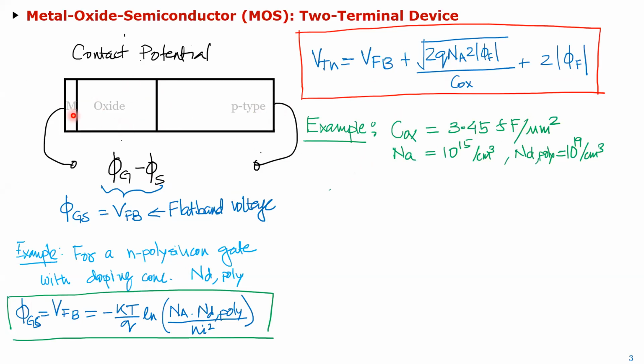And let's say I have doped this p-type with 10 to the power 15. So it's what's called lightly doped, because that's what I usually want for the substrate. And then this one I have heavily doped, 10 to the power 19, because I want it almost close to metal. And why don't we have metal? Why don't we just put metal? That's a processing question. Maybe we'll answer it some other time, or I can answer now if somebody has a question. But that's the poly type.